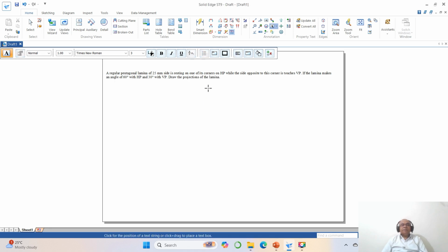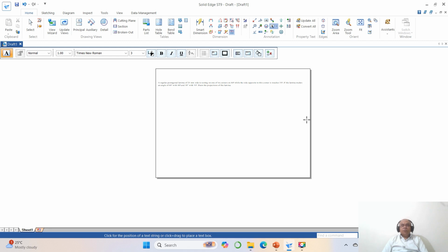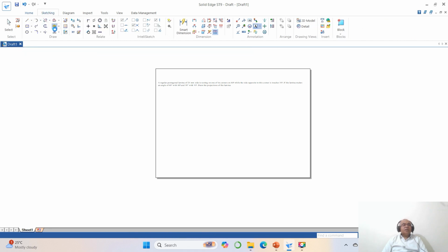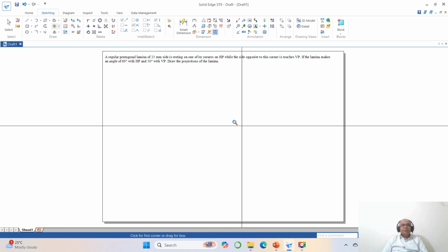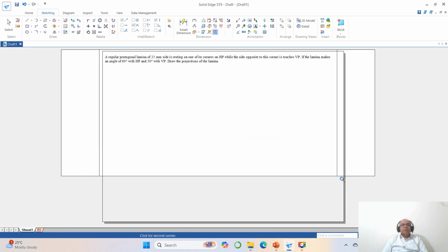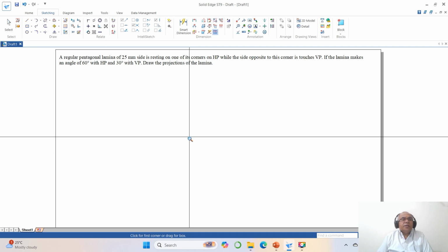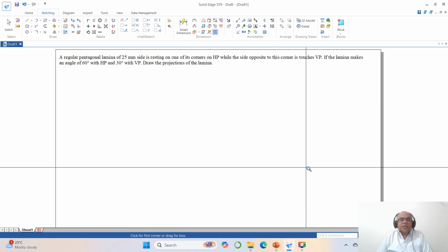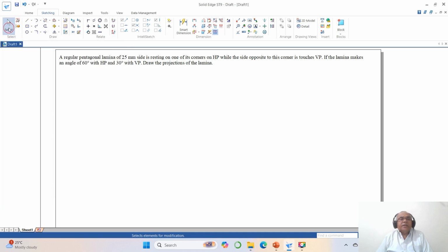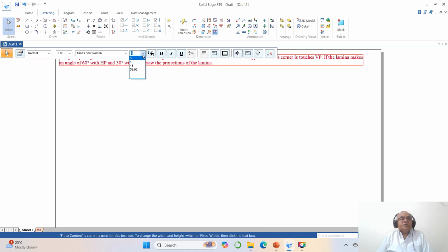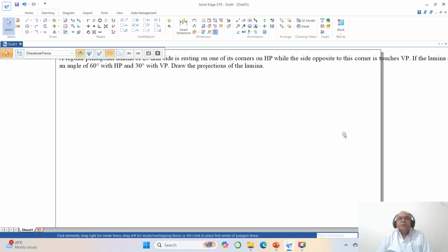Okay, then just right click. Now you go to move, come down to sketch, click on move, disable copy, select this and move it here. Then come down to fit, then go to zoom window. Now I need to write the sketch. Here what I have done, I have taken a 3 mm side. I will show you how to change this to 4. You just click on 4. Now you can see it has been changed to 4.